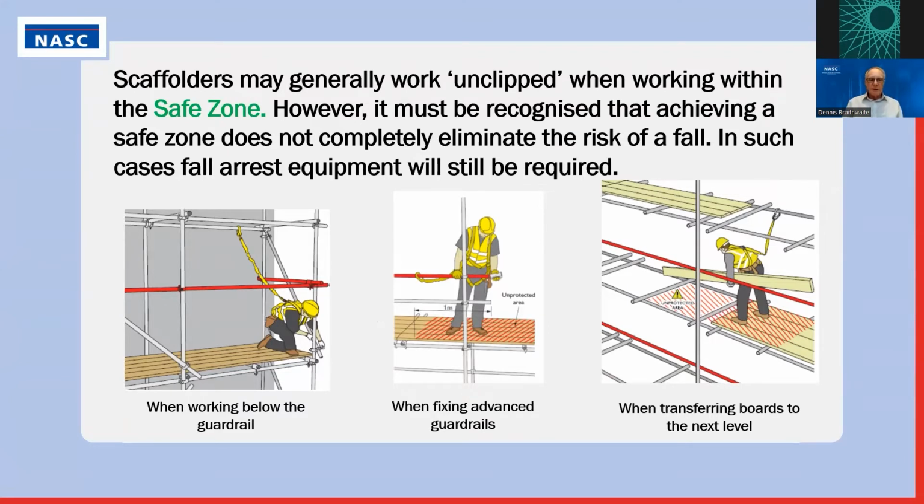For example, the diagram there on the left, when he's working below the guardrail, he has to bend down below the guardrail to fit the braces and various other things. So he has to clip on for that. When he's fixing advanced guardrails, and I'll come on to advanced guardrails shortly, and when he's transferring boards, because when he's transferring boards from one level to another, he's creating a hole in the platform for himself.